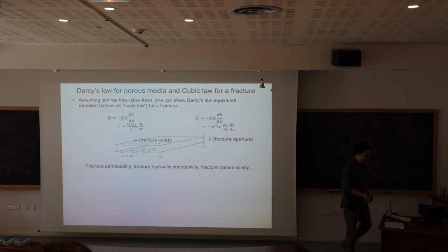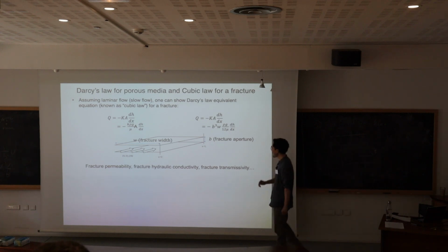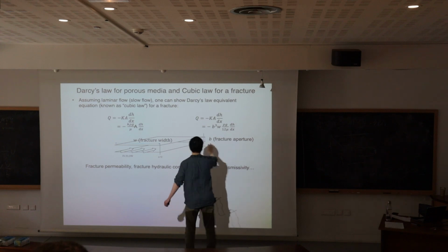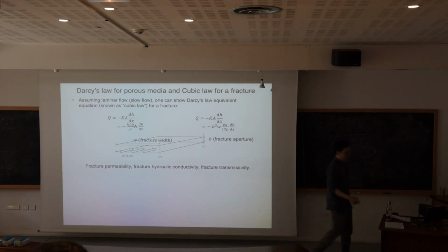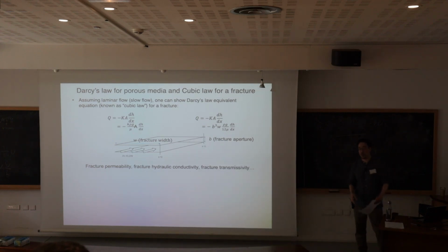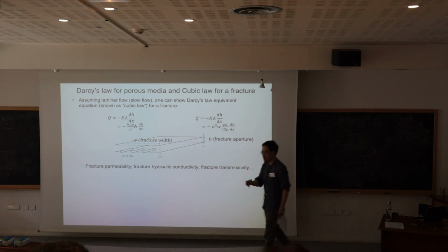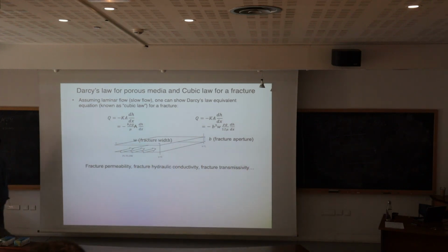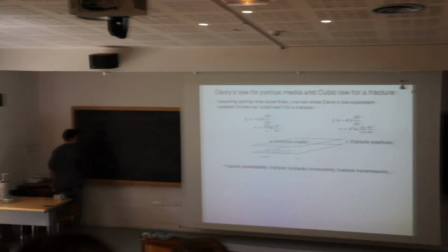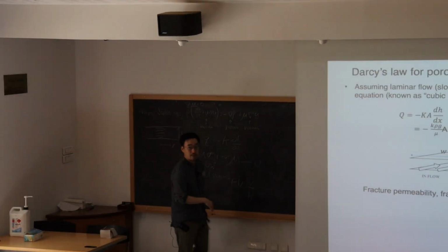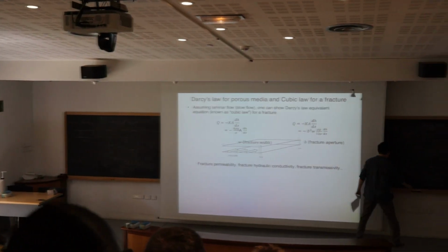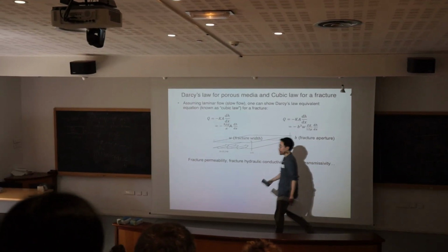Great, I'm very happy. Okay, so that means I won't get to the end of my lecture, but I'm still happy. So I think it's really informative to see where the cubic law is coming from, because if someone asks what is the one thing that you have to know about fractured rock hydrogeology, I think arguably it will be cubic law, right? And you want to know where it is coming from. And what's nice is it comes from the Navier-Stokes equation. And I can show that in a few minutes without too much algebra.